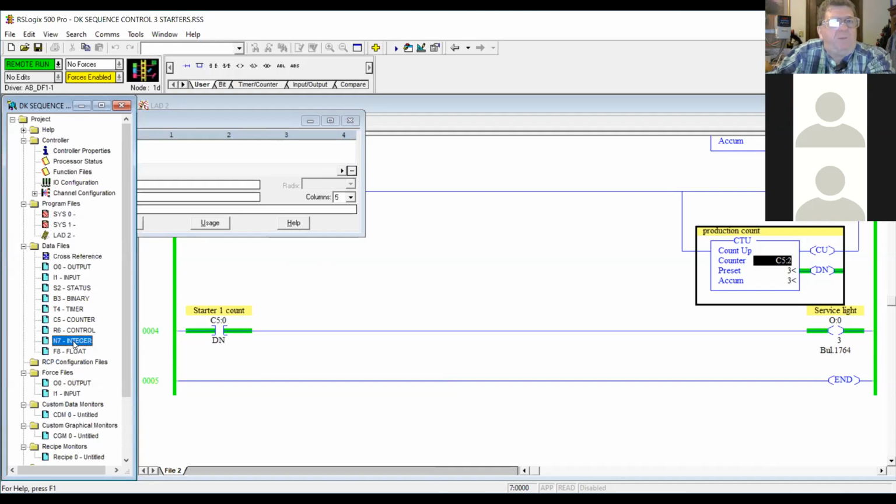So if you've got whole numbers that need to be stored in your program or process, they're in the N7 file. If you have floating point numbers with decimal portions like 100.9 or 300.76, they're going to have to be in that floating point data file, because that's the only place that allows decimal portions like that, where the decimal can be in different places.